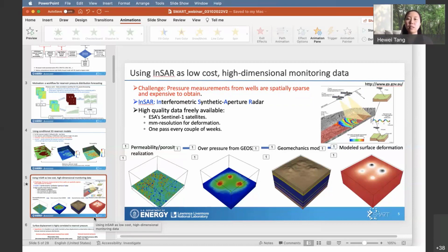And this does need effort, but it's achievable. For example, since InSAR data are really high frequency, I did see in the literature methodologies that average the InSAR data over a full year span so that they are able to get good quality InSAR data representing that year.